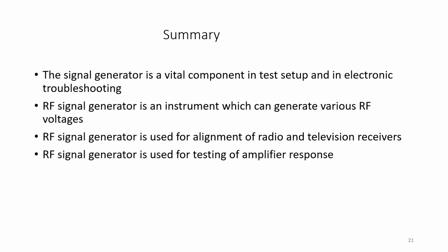The master oscillator is tuned by a motor driven variable capacitor. For fast coarse tuning, a rocker switch is provided which sends the indicator gliding along the slide rule scale of the main frequency dial at approximately 7% frequency changes per second. The oscillator can then be fine-tuned by means of a large rotary switch, with each division corresponding to 0.01% of the main dial setting. The master oscillator has both automatic and manual controllers.